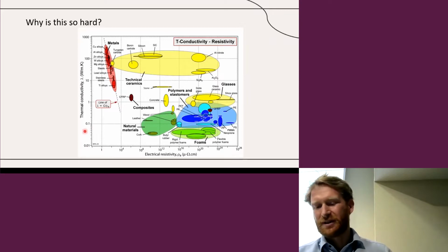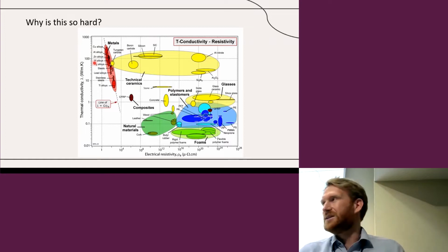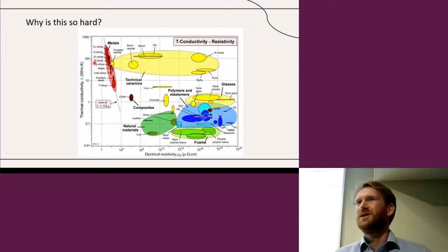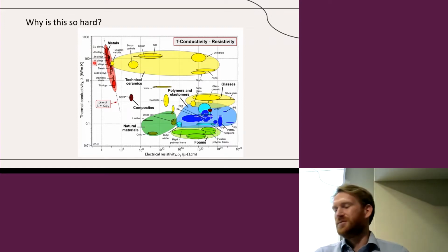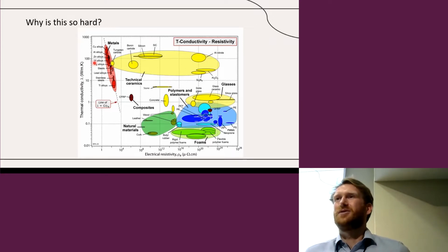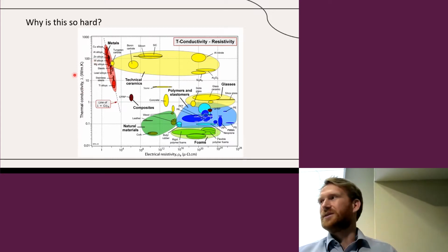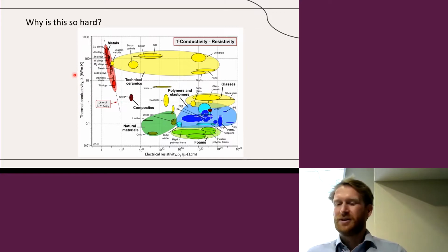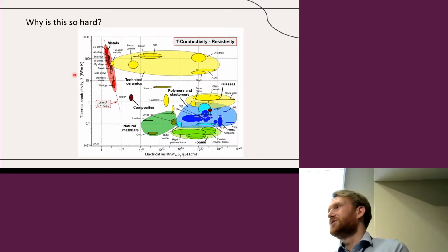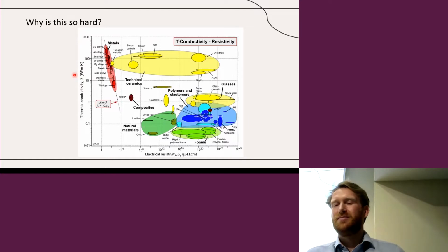But instead, if we look at the axis for the thermal conductivity, the range is less than 5 orders of magnitude. So while for bulk systems this is not an issue, once we go to nanosystems where the dimensions of your system become easily 6 orders of magnitude smaller, this becomes a problem. You cannot just ignore what is going on in the substrate anymore. So you need to use special techniques to eliminate the effect from the substrate.